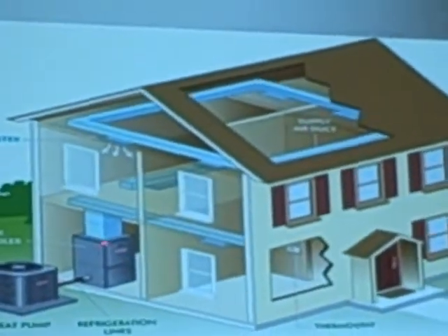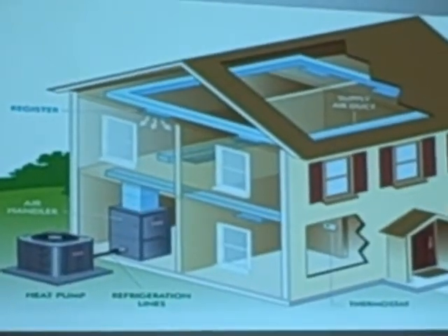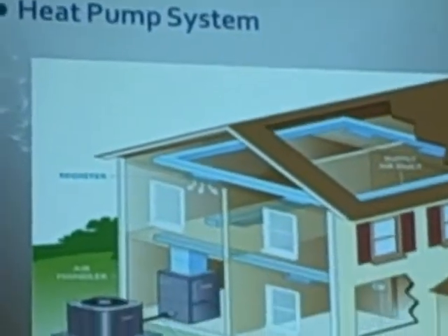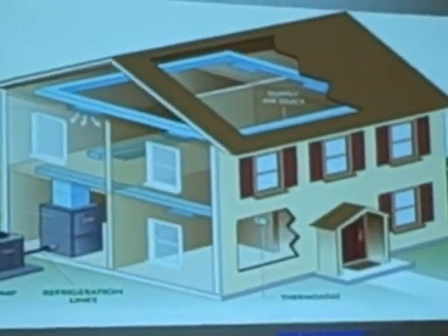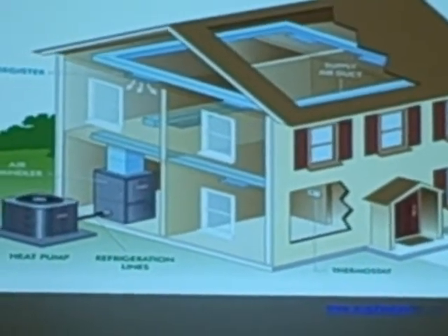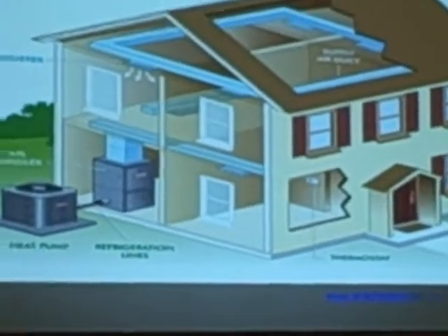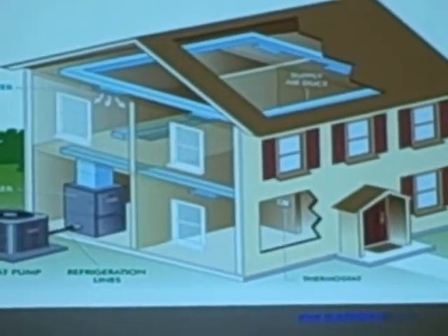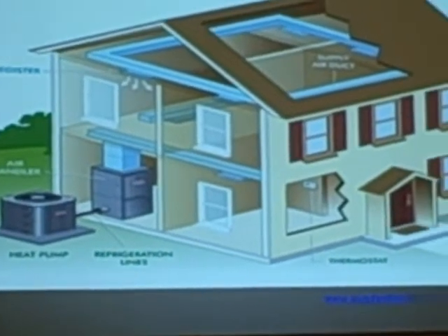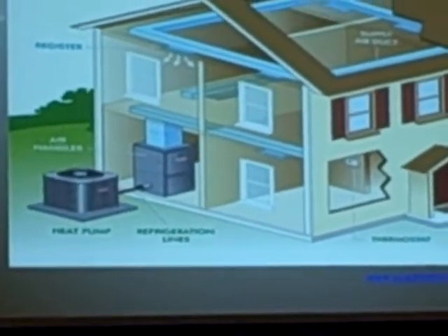So typically in an air-to-air heat pump, this is a heat pump here, and air-to-air, the same process is occurring. This coil either gets hot or cold, and it goes to the ductwork, and it heats and cools your house. These systems in the 80s really got a bad name for themselves, because they weren't highly efficient, they would blow maybe 85-degree air. Well, you can heat your house with 85-degree air or 80-degree air, but most people felt drafty, and they got a bad name because they didn't have enough lift. They didn't have enough efficiency to them. Even today, that's changing quite a bit.